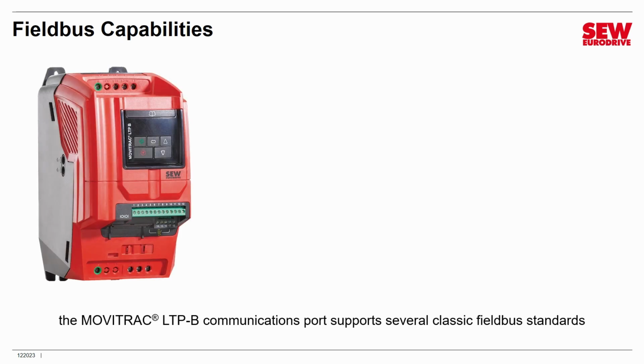Let's just review the field bus capabilities of the MOVITRAC LTP-B. I introduced these way back in the beginning of the class, but maybe you've forgotten about them, so a quick review is in order. The MOVITRAC LTP-B communications port, which is right here, supports 3 classic field bus standards: SBus, Modbus RTU, and CAN-open. What do I mean by a classic field bus standard?